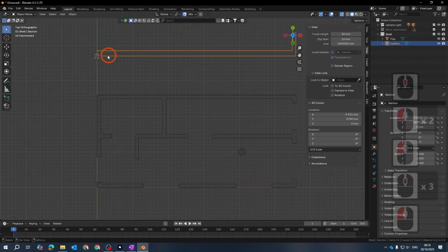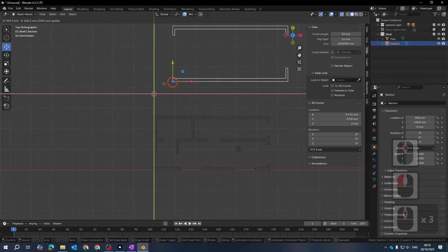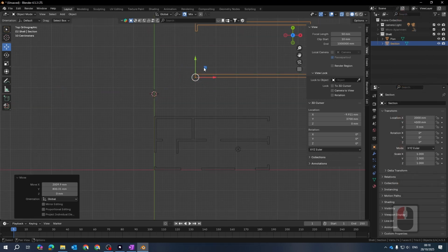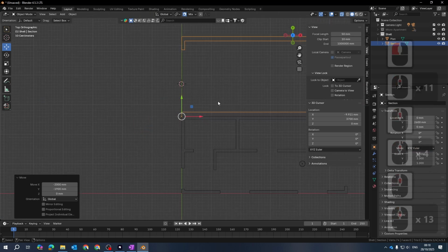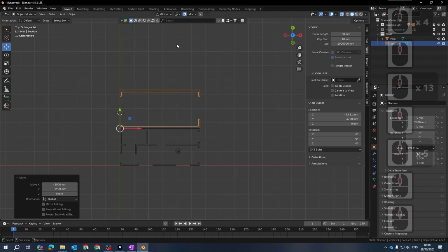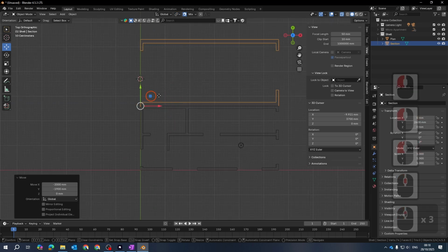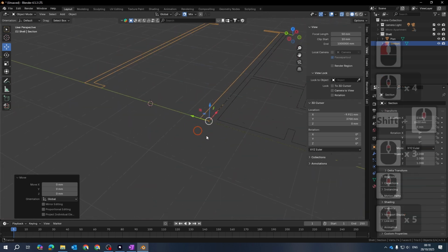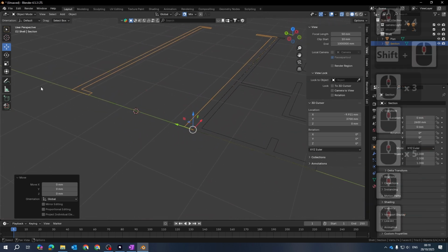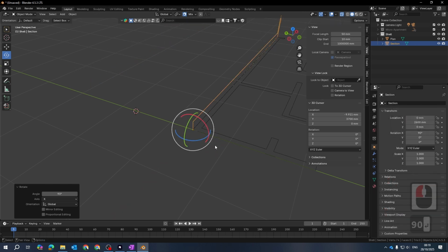So why do we want to do this? If I move this object now outside of edit mode, you'll see that origin becomes a point by which to rotate and move accurately outside of edit mode. This is very important to understand because that's its individual origin. So that's the origin of this file now. I can move it to this location, and if I go to 3D view and switch around, I can use the rotate command. I can rotate this object now by 90 degrees.